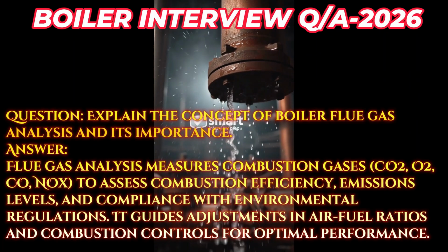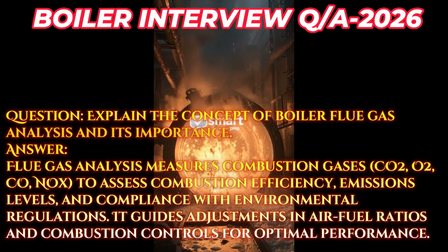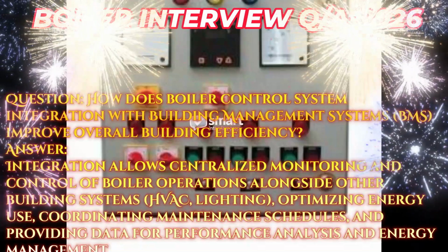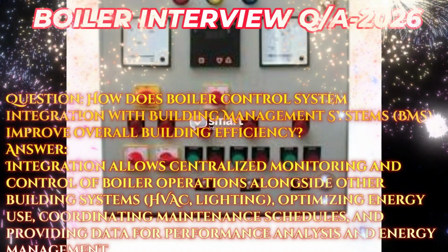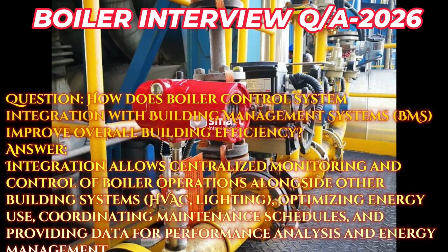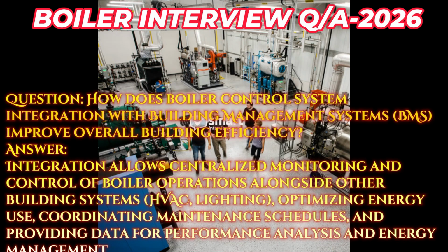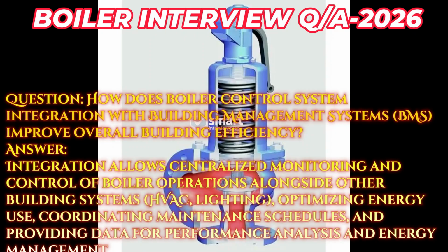It guides adjustments in air-fuel ratios and combustion controls for optimal performance. Question: how does boiler control system integration with building management systems, BMS, improve overall building efficiency? Answer: integration allows centralized monitoring and control of boiler operations alongside other building systems, HVAC, lighting, optimizing energy use, coordinating maintenance schedules, and providing data for performance analysis and energy management.